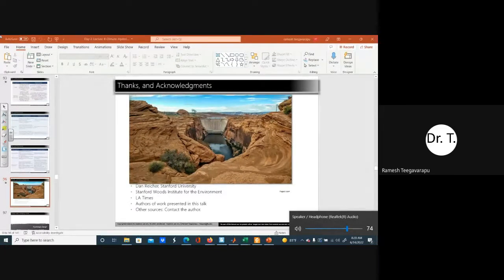They saw that improvement, and now they are going to replicate it to all other reservoirs to improve their operations. Now, the crux of the whole technology is to have accurate forecasts. If your forecast is wrong, then releasing extra water just to create storage for incoming water may be catastrophic, because in some cases the reservoir operators thought we might get a flood and so they had to release the water. When they released the water, the anticipated flood didn't come, so then they have problems with water supply and irrigation. So the viability of operations depends on the accuracy of the forecasting tools you are using.